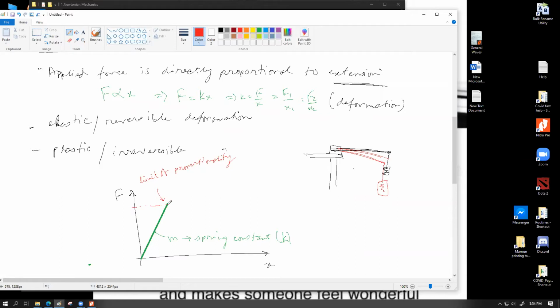So let's say if we apply more force, the typical way objects behave beyond the limit of proportionality, it goes on like this. It takes a bit of a curve of decreasing gradient. It reaches up to a peak, and then it can start falling downwards. Beyond this point, we can have a lot of different falling lines for different specimens. But ultimately, we can have a breaking.